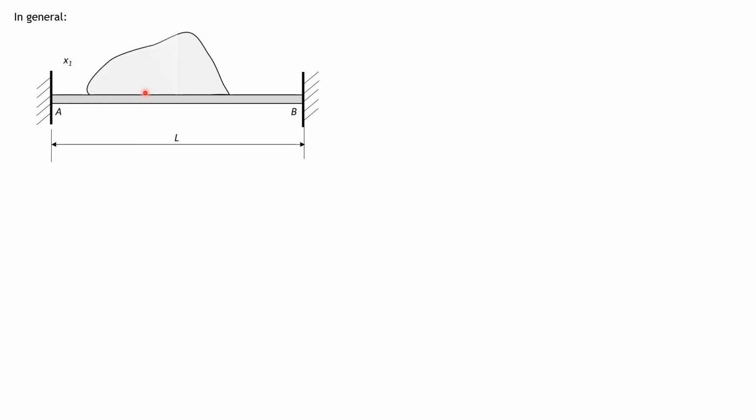So in general, let's develop the fixed moment formulas for the general loading. So if you have this general loading here, the idea is to consider a strip. Then that would be height of strip y times thickness dx, that's the differential p.